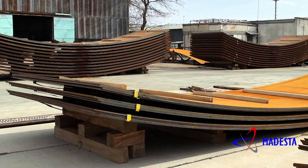And if the shell material is of a very high thickness, made for the tank, then it should be prefabricated. You should do pre-bending and prefabrication, and those prefabricated sheets you have to bring outside and then do the welding as per the jacking method. So this is all about the tank manufacturing.